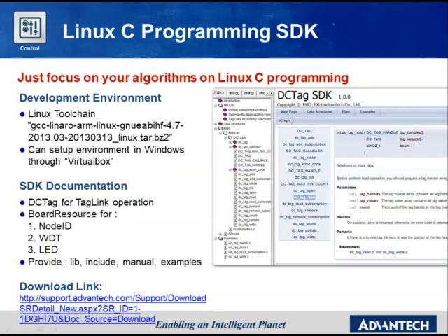For the IT-based background user who is not familiar with IEC-61131-3, we also provide another approach to programming, and they could just focus on the algorithms for a Linux C program. We provide the Linux C API with detailed examples and help documents. Users could use the library we provide to develop the Linux-based program and then download it to the ADAM3600.